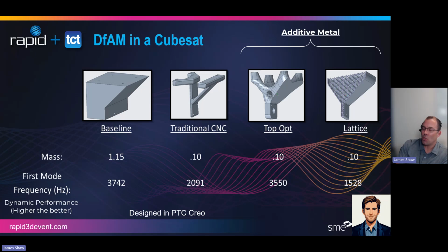And then compared that to 2 additive metal processes. One is topology optimization, which is this algorithm-based software which can, for a given shape, remove material in the most efficient way, and provide this beautifully organic and efficient geometry that can be printed, versus a slightly different approach, which is a lattice infill. And there's a variety of different lattices being engineered nowadays to satisfy a lot of these structural requirements.